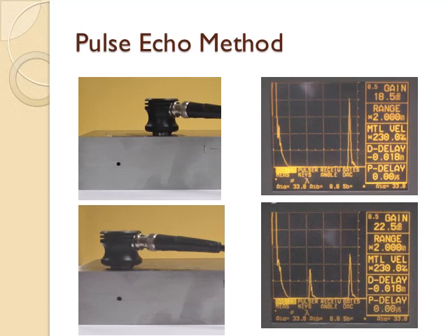On the other hand, if there is any defect in the specimen like a small hole or pores, then ultrasonics will be reflected by the holes, because we know the principle: whenever there is a change in medium, the ultrasonics will be reflected back.